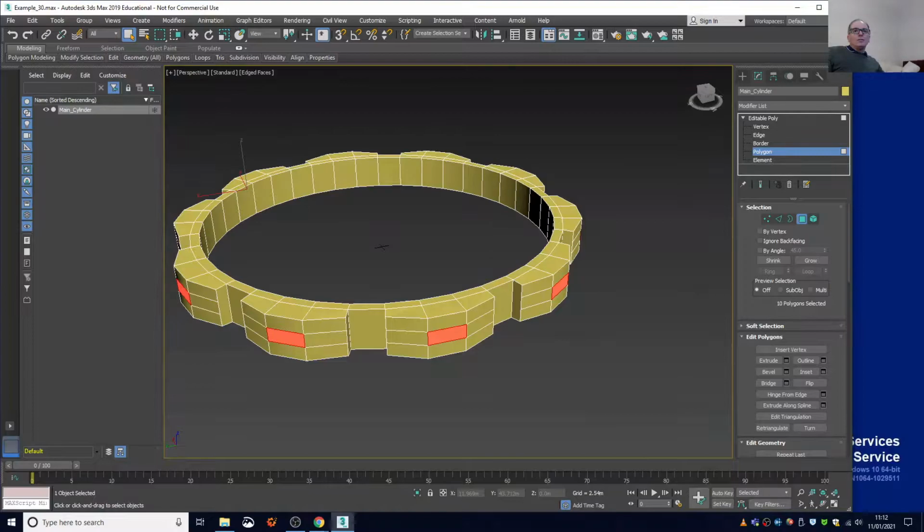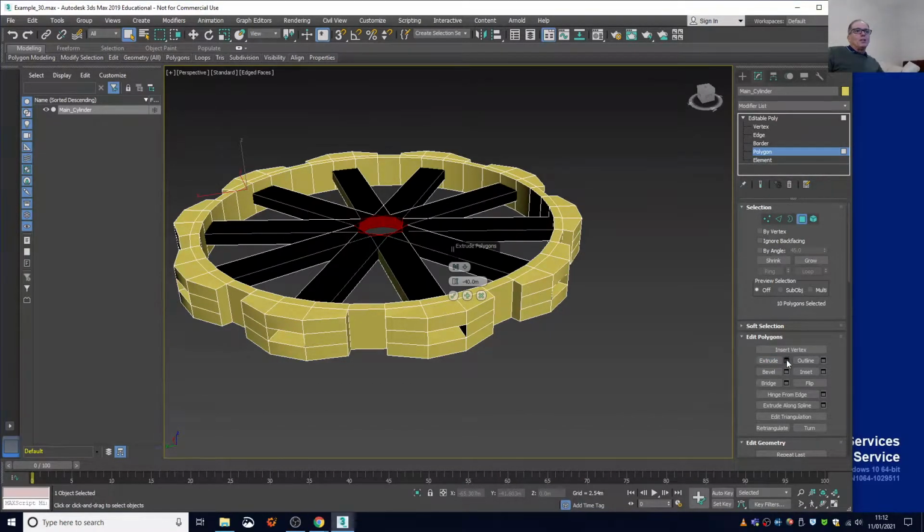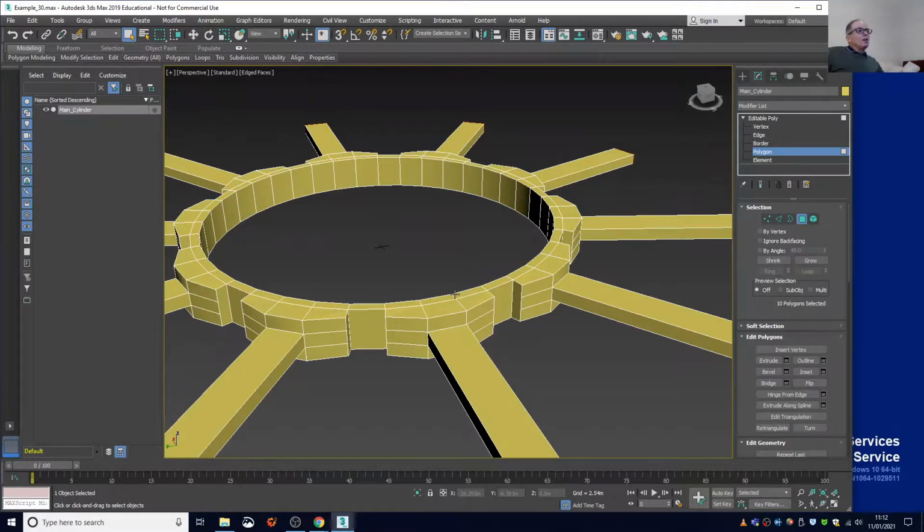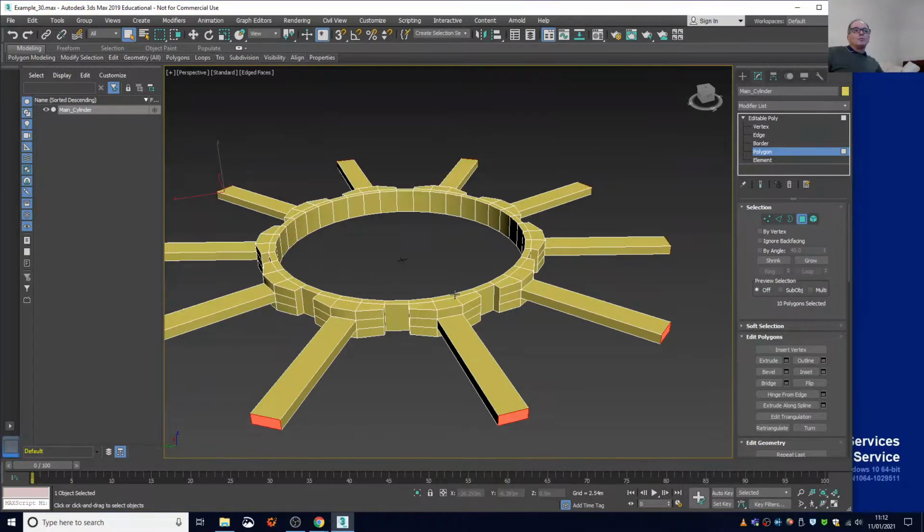And we do an extrusion by clicking on the Extrude button here in the Edit Polygon menu. And we specify the length. So we don't want minus 40, we want actually 40 meters. And then we have to click, otherwise it doesn't happen. So now we have extruded our shape to have this level.